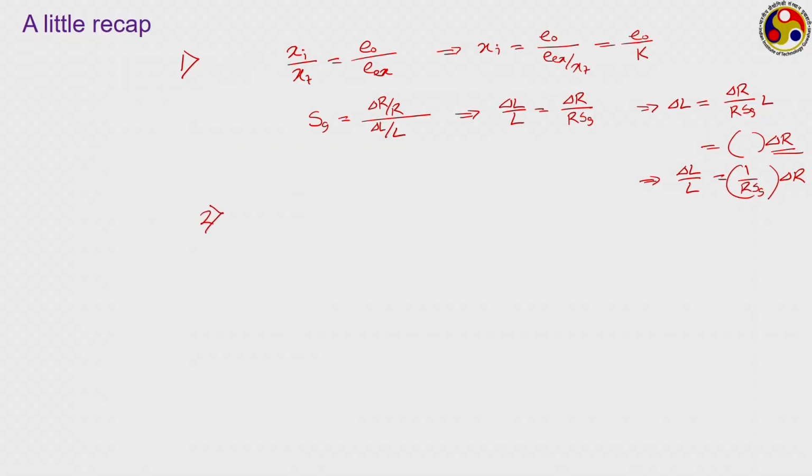The second group of instruments is where we talked about the LVDT, which actually depends on the change of inductance with the change in length. We have discussed this in detail, about how it gives a linear behavior, that is, with the change in the core position the voltage induced in the secondary side changes, and with a proper arrangement, generally the series opposition configuration, we can get a perfect linear representation, that is, output voltage can become a linear function of the displacement.